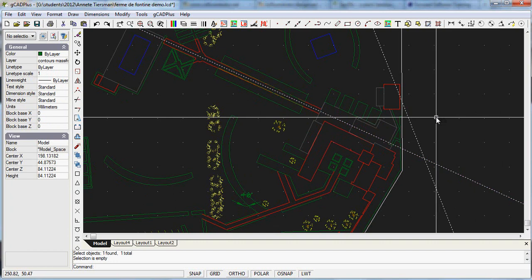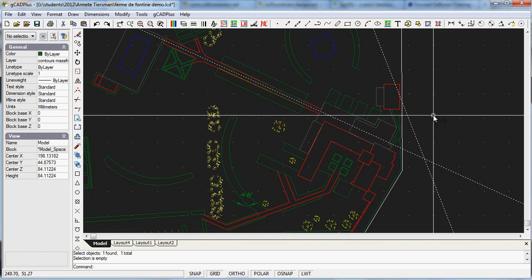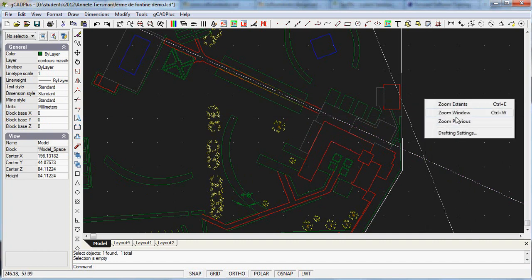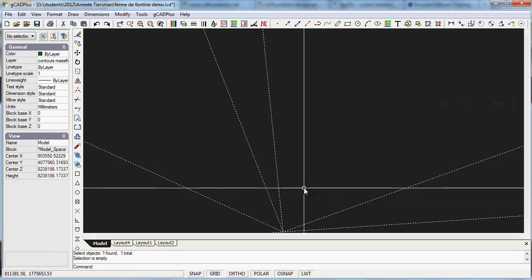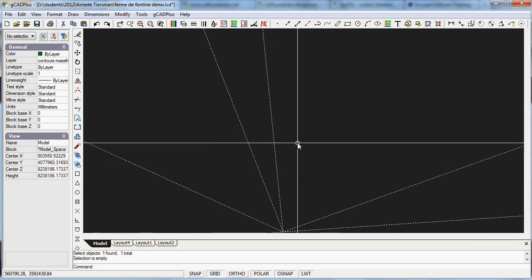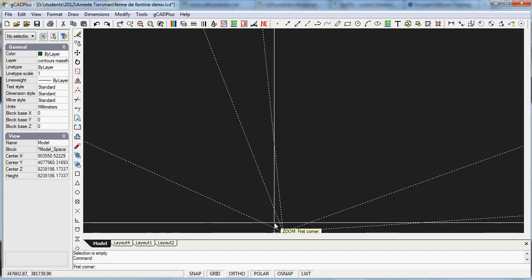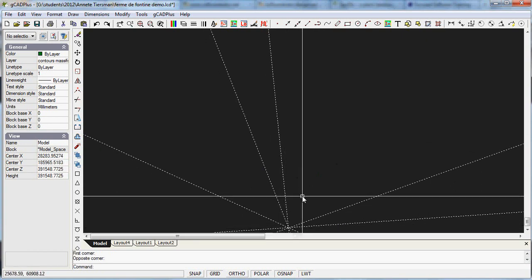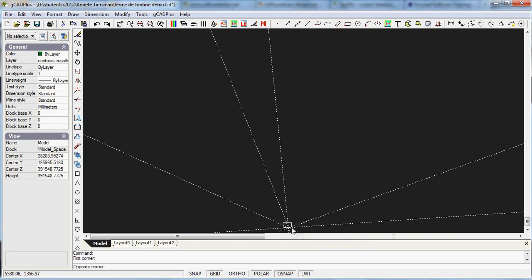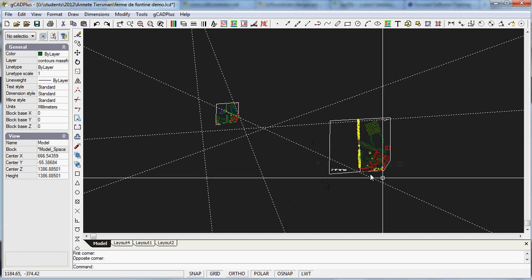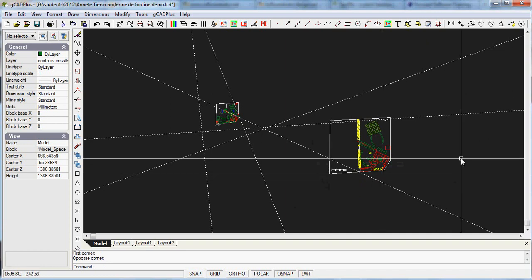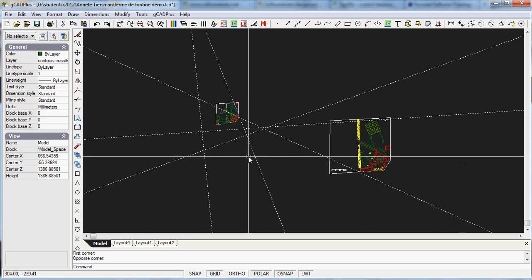What's interesting about this drawing is we have told you in other videos that construction lines and rays shouldn't affect zoom extents, but if I right click now and go zoom extents, you can see the effect here. The construction lines just radiate out and we can't see the design itself. In fact, the only way to get at it is to do a zoom window, repeat that, and we can get back to where we were, and that's extremely tedious. So there's some entity, I suspect, in this drawing that's way out, maybe several entities way out to the side, and it's causing this level of grief.